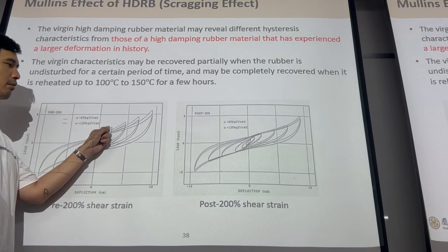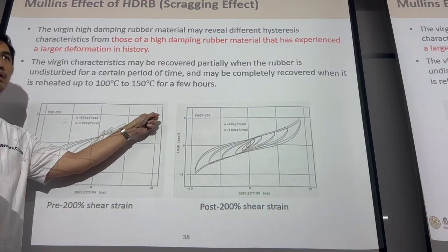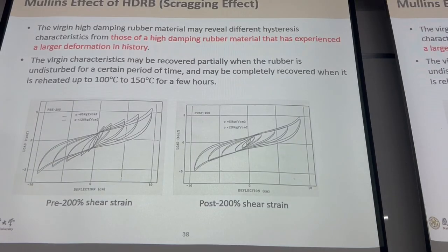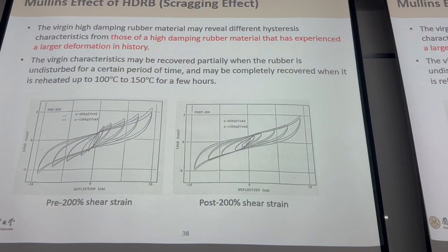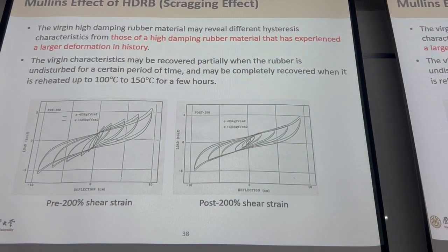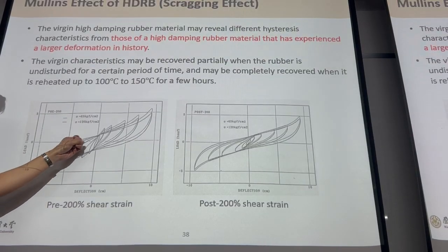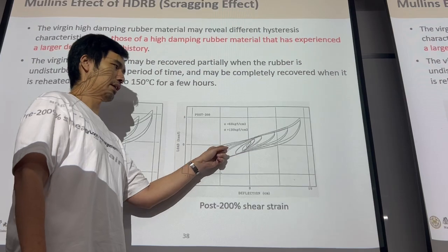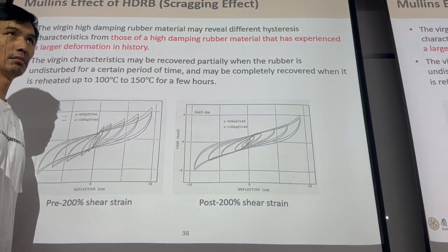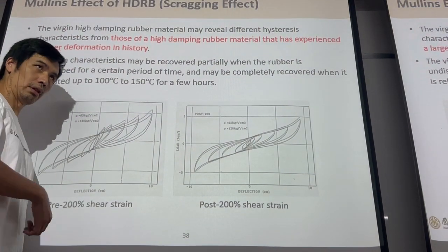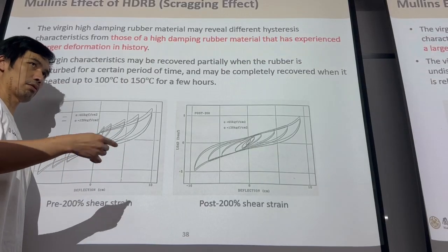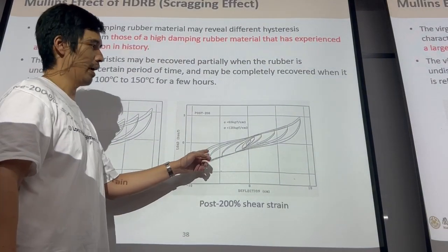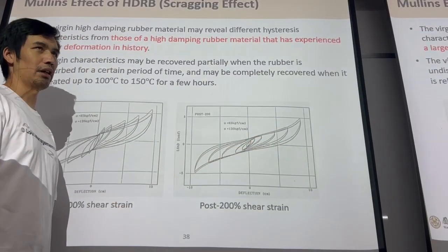It has a nice feature, but you will see a little bit of hardening effect when you turn around from loading to unloading. Okay? Then, if you do a little bit of cycling first, afterwards you can get a better behavior. So, the first few cycles, you will see this hardening effect. Afterwards, it will be a little bit more stable.